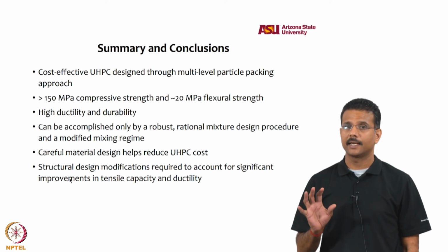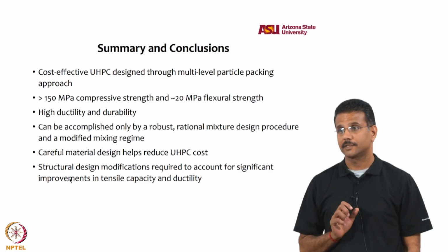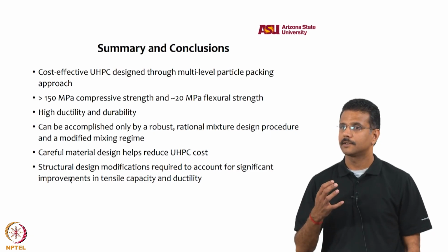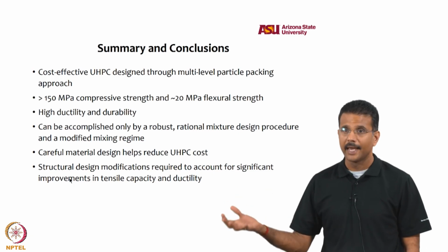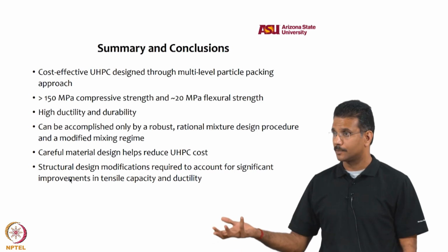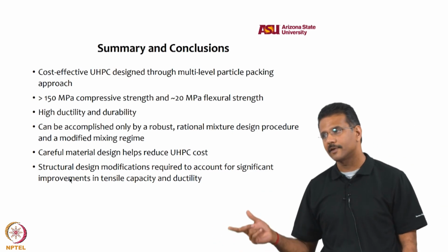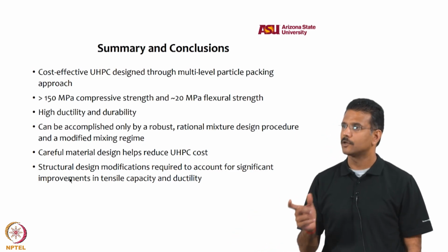These properties can only be accomplished by a robust, rational mixture design procedure. You can't use a general mix design procedure from any of the standard available methods, which are mostly water cement ratio based. You can't do that. Water cement ratio is basically a secondary parameter here. First is always packing.